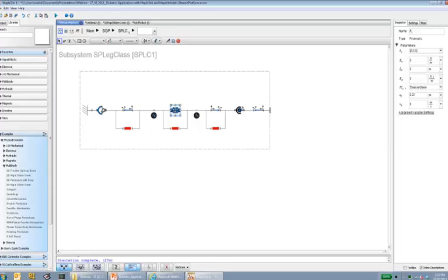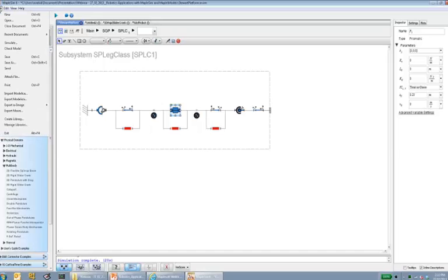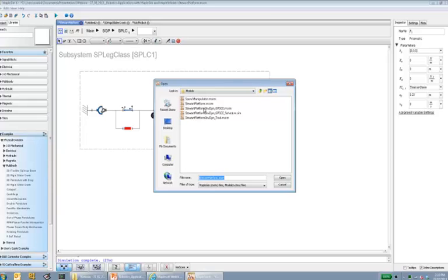Then the inverse dynamic part is, now that we have that, let's say we want to implement a controller and we want to do design, we want to know how much force we need to actuate the system with. So the force required for the specific motion, depending on velocities and acceleration that is the desired trajectory of the platform, is calculating those is the inverse dynamic part. So let's start with the simplest way of accomplishing these two tasks, and that will be by tandem, basically using 2 models, one for inverse kinematic calculation and one for driving the system.